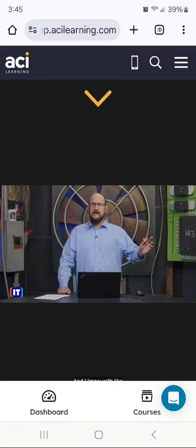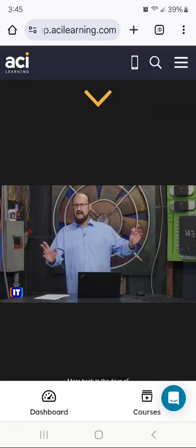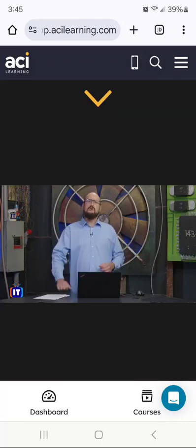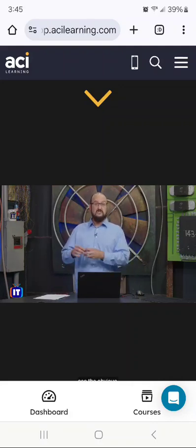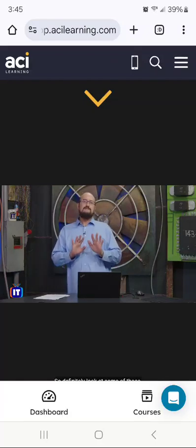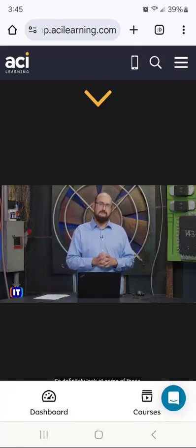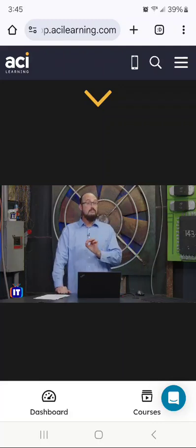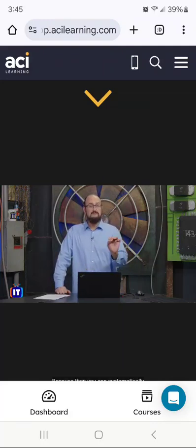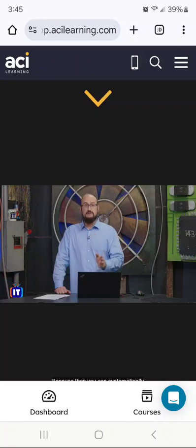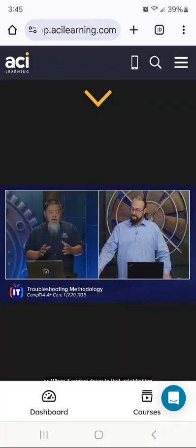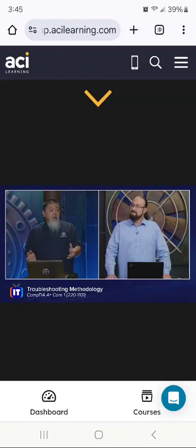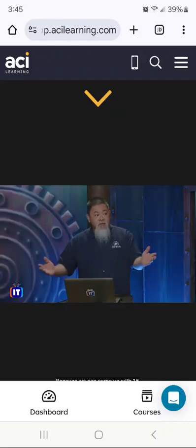And I know with things like HDMI today, it's becoming a thing of the past, right? More back in the days of things like VGA and stuff, would you see bent pins, right? And maybe a connector, or maybe something on a motherboard where you can see the obvious, maybe a swelling capacitor, right? So definitely look at some of the simple fixes first, right? And consider multiple approaches, right? Because then you can systematically knock them off a checklist, and then you can move into that next step. Yeah, when it comes down to establishing a theory, we want to have at least, let's say, 2 or 3, right? Because we can come up with 15.